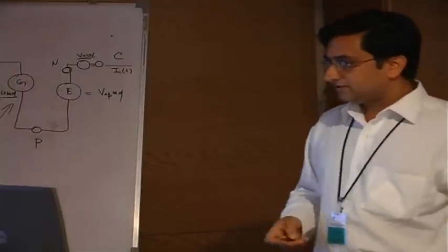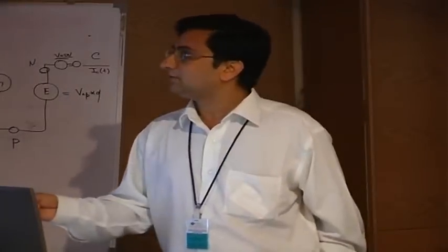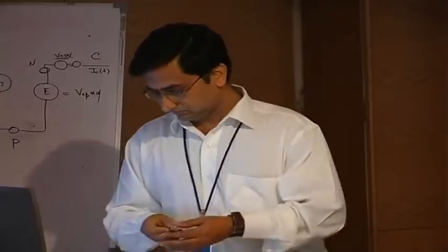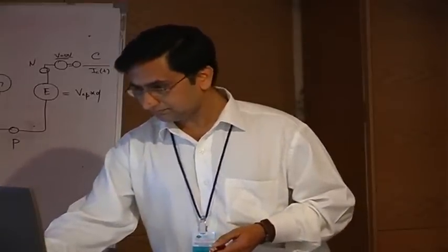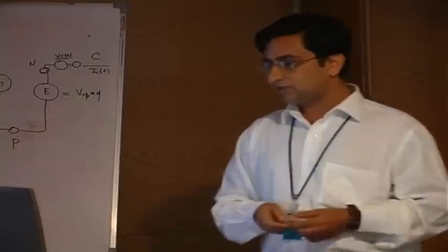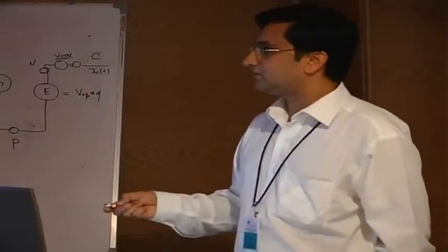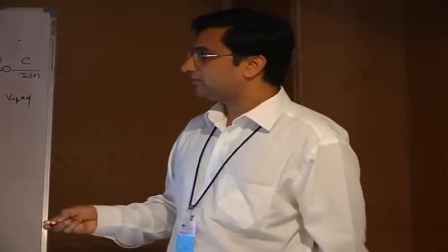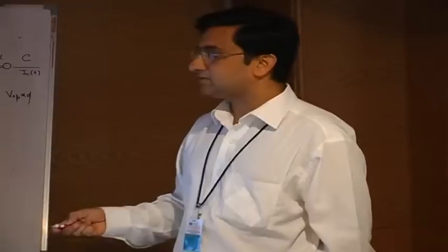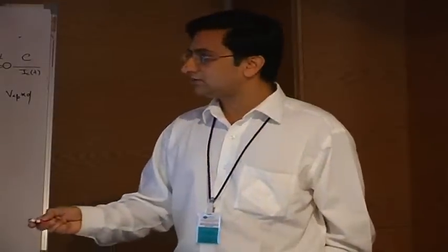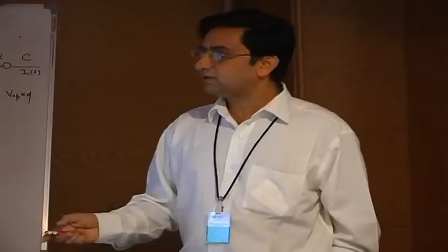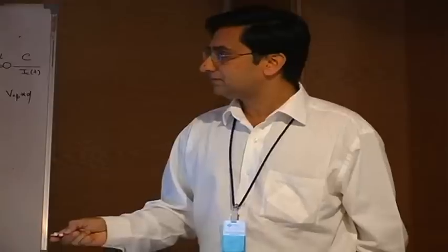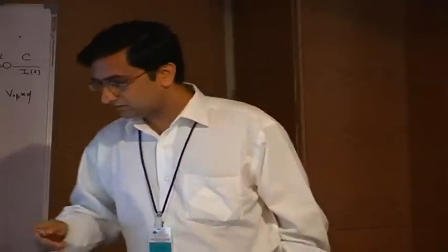This is a DC characterization that I was talking about. You can use data sheet, test data, and use the characterization tool. And this is what you can expect from Simplorer. This is on a single desktop. You are viewing a circuit, you are viewing blocks, you are viewing state machines. So utilizing all these three tools, you can simulate the complete problem. You can see here the motor which is coming from Maxwell. So in a single window, you can expect this.